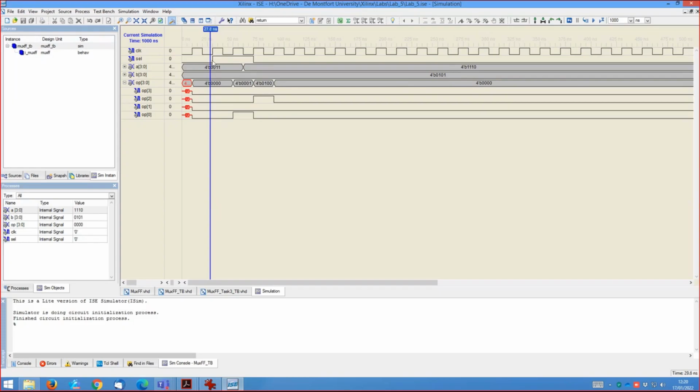So essentially, it will not register until the next rising edge of the clock, which is why we always should avoid this sort of situation that the clock arrives before a signal is settled. So that's why basically we only see that change in the output here, and then this one and that one, which are matching, lead us to an output of 0001.